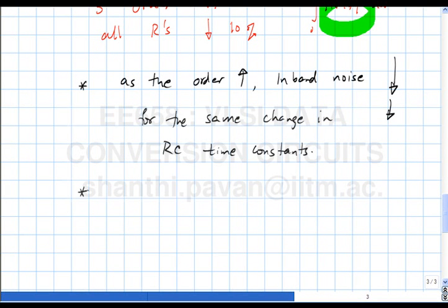Yes. In this particular case, we have just a plain integrator, 1 by Ks, where we can see it either as a gain change or a bandwidth change. In a higher order modulator, this will show up clearly as a bandwidth change and not as a gain change, because the gain will depend upon the components. In a first order system, gain or bandwidth is the same thing.